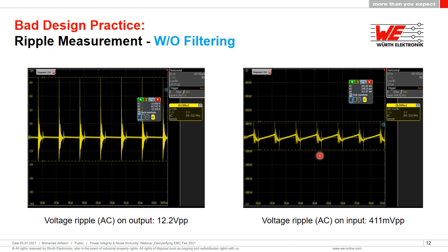to put across that with a very decent oscilloscope and a really good voltage current probe, you are able to debug a lot of your EMC or EMI issues using the oscilloscope. You don't necessarily need to go and test into a test house. You don't necessarily need to also have a receiver, an EMI or spectrum analyzer. You can, with something like this RTO 2014 that we've used, either in an FFT mode or even time domain mode, as you can see here, identify some of those issues and some of those frequencies that you have got an issue with, and accordingly introduce suitable solutions well before you go into the EMI test lab.